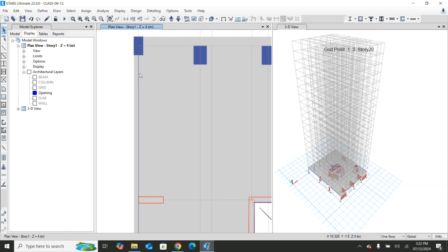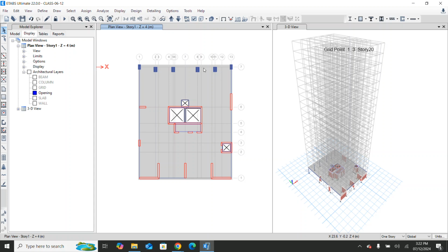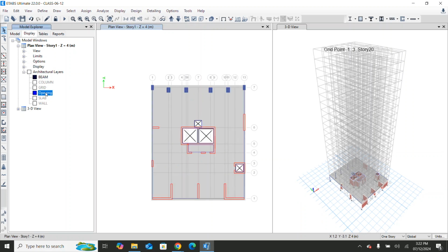The top. Here we have the beams. No, on the left we have this top side. Yeah. Actually, in that CAD plan there is no beam, but normally we need the beam over there, right? So I'll just make one more beam over here. For example, if it is not there in the CAD file, then we have to make the beam. Then what to do? We'll just go to this beam. I just turned on that layer, that's it.